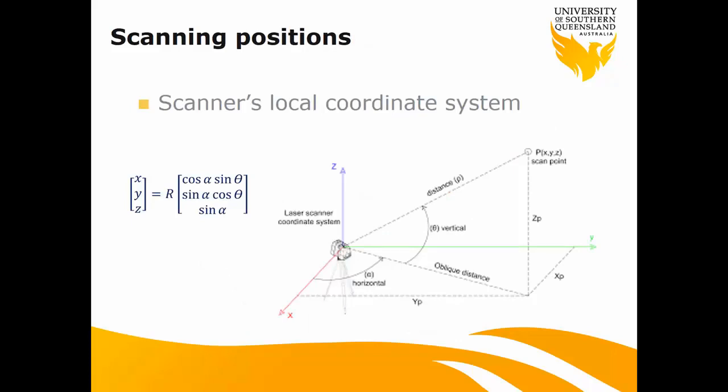Directly collected data is the point data in three-dimensional space. That means you can represent your point data in coordinates x, y, z, or easting, northing, after you transform your laser scanning points from one coordinate system to the other. But directly, the point is represented in a local station coordinate system.